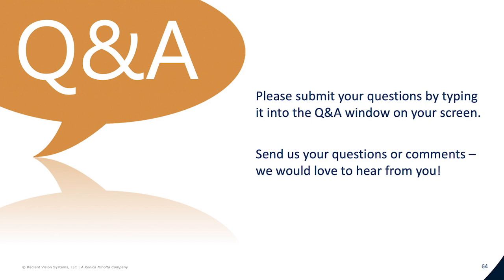on an OLED or a micro LED, then having really high resolution is important. We want to be able to maximize the number of imaging system pixels to the display pixels. So perhaps we want to have 5 or 10 or more imaging system pixels for every single display pixel. Thus, we need high resolution for that type of application. But if you're looking at doing something like basic uniformity testing, where we don't actually need to see every single pixel, then much lower resolution may be acceptable.